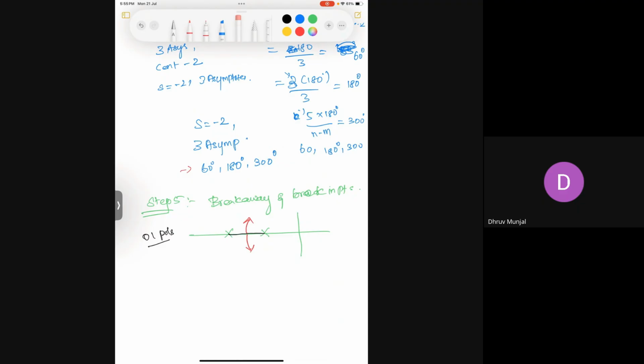Now, this is the first example. The second example, if there exists a root locus in between two adjacent open loop zeros, because when I take a test point here, I will have only 1 zero here, then this will be in the root locus.